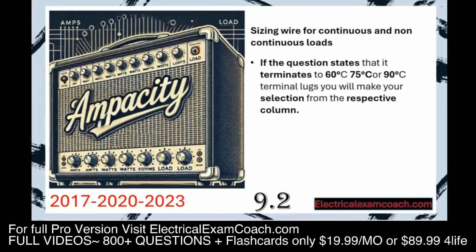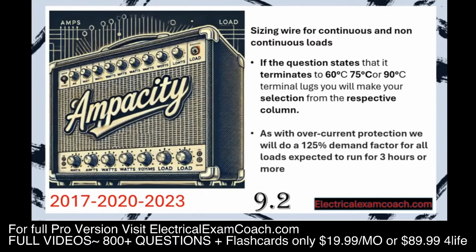If the question states that it terminates to 60, 75, or 90 degree C terminals, we're going to make our selection from that respective column under normal circumstances. And the second one is, as with overcurrent protection, like we learned before, we're going to do a 125% demand factor for all loads that are expected to run for 3 or more hours.